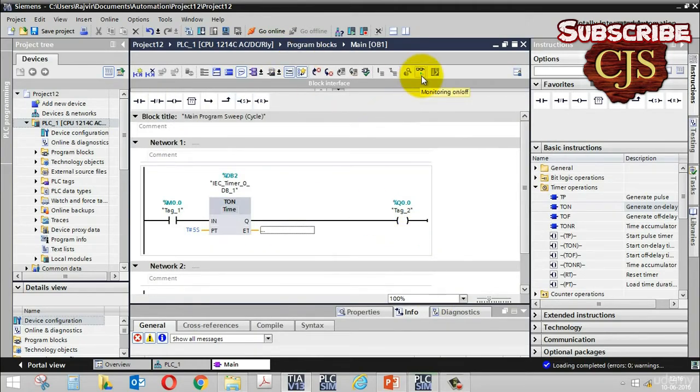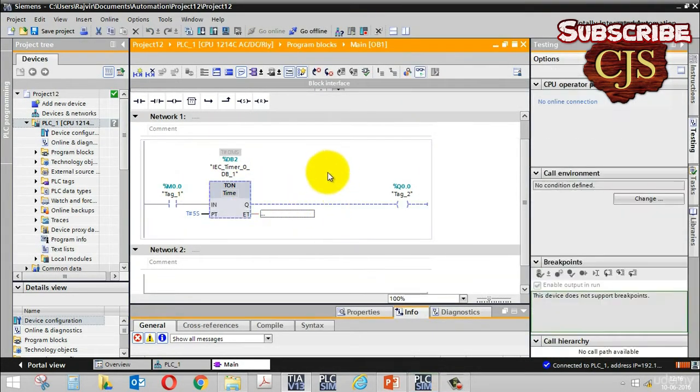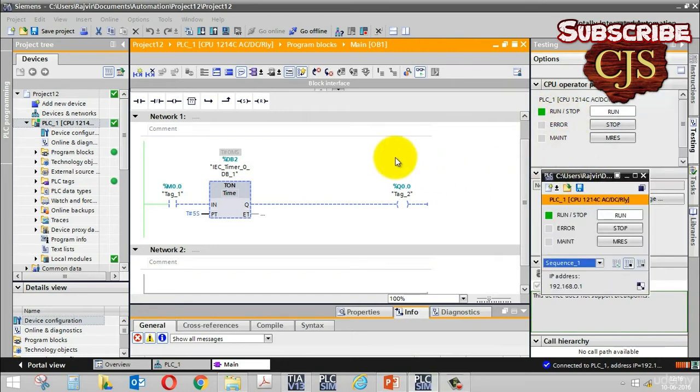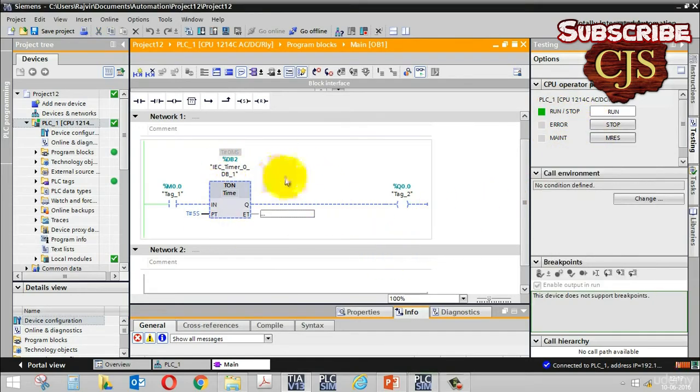Next we can go to simulation, monitoring on/off. This is the step by which you can notice your action going on in the PLC. So this is on, and you can see this panel here, this is the same simulation panel. So PLC is at run mode, programming is downloaded, and there is no physical PLC, but you have the simulated PLC here. Okay, so we are in the run mode. Now we can execute the software, this ladder logic, to see what's happening.